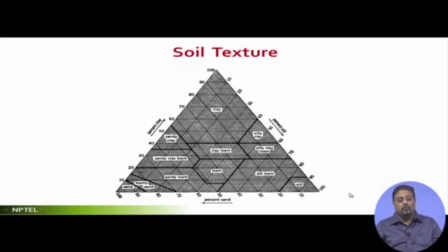with respect to this, empirically, also studied in the fields and in laboratory tests, it has given a classification of texture depending on a range of composition of sand, composition of silt, and composition of clay. How to read this? When you are checking what percentage of sand, it starts with 0 here, 10% of the sand, 20% of the sand.